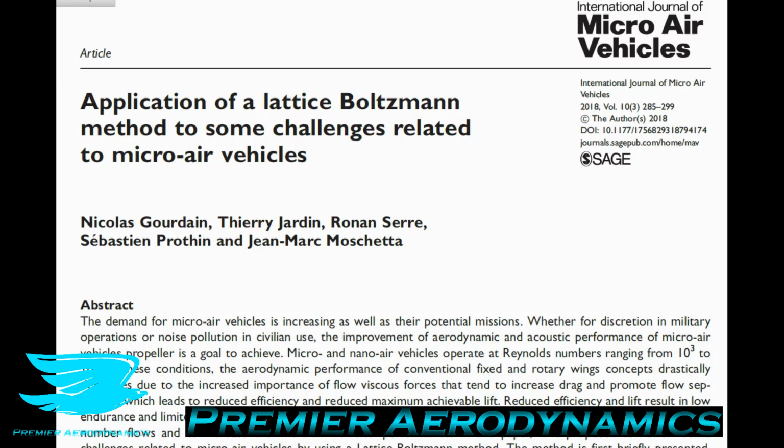Now, theoretically, I guess you could make the grid so fine that you're looking at every particle. However, there are some limitations to that with the Lattice Boltzmann method, and that is because the grid is usually linearly split up. You can't really have refinements, at least not yet. There are some programs that are looking into refinement zones, but generally speaking, the entire simulation that you have will be uniformly divided. So that's very different to the Navier-Stokes CFD, where you can refine certain areas, you can put boundary layer meshes, and that's a very powerful thing that Navier-Stokes CFD does have.